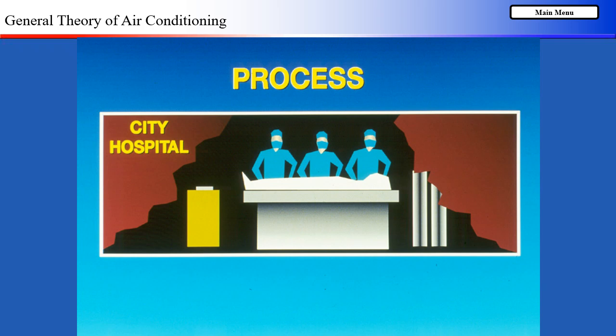While comfort work has people as its object, process air conditioning has things as its object. Process work seeks to condition air as necessary to make the production process more effective. Applications are found in the manufacturing of textiles, printing, electronics, and pharmaceuticals, where precise temperature, air cleanliness, and other conditions are critical. Textile manufacturing, for example, requires an atmosphere with relatively high moisture content, while multicolor printing demands constant temperature and humidity.